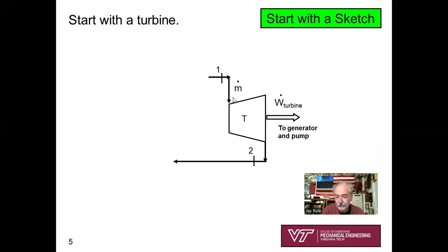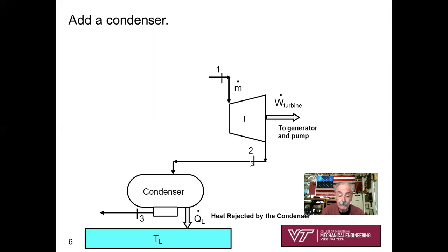All right, so here's a sketch of our turbine. See, the pressure is decreasing from 1 to 2. That's why I'm showing it's an expansion process. See, W dot of the turbine. So you might say, well, where's your Q dot in 1 to 2? I haven't shown anything, have I? That's because this turbine is going to be modeled as fully insulated. Okay, so there's our turbine process. In at 1, out at 2.